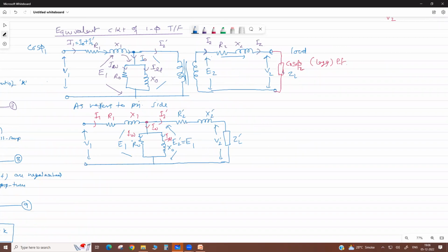Okay, now let us see, my dear, this is the magnetizing branch. This branch is responsible for your core losses and magnetic flux. Now, you know, these core losses depend on your frequency and voltage. Okay. So, as I told, suppose this V1 and V2 are very close. Actually this is the exact equivalent circuit of the transformer.